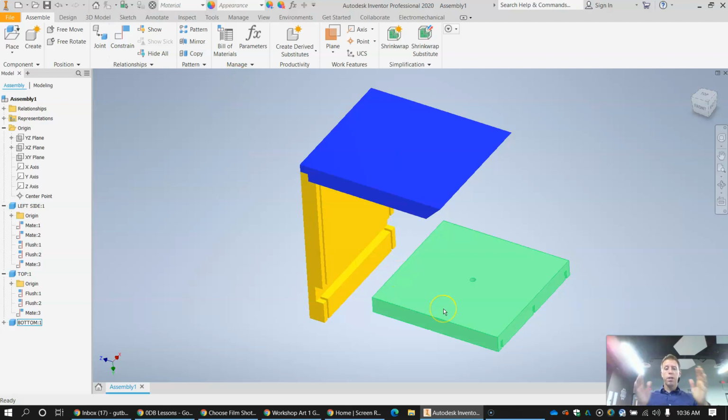So if you're trying to constrain something together and some of your dimensions are off, you're going to get an error. So if you did 0.38 for your thickness or the depth, that's going to cause an issue. 0.38 is rounded up from 0.375. 0.375 is the same as 3/8, which is half of 3/4.